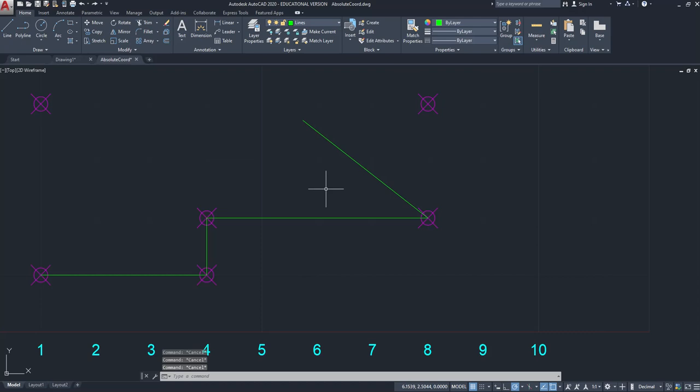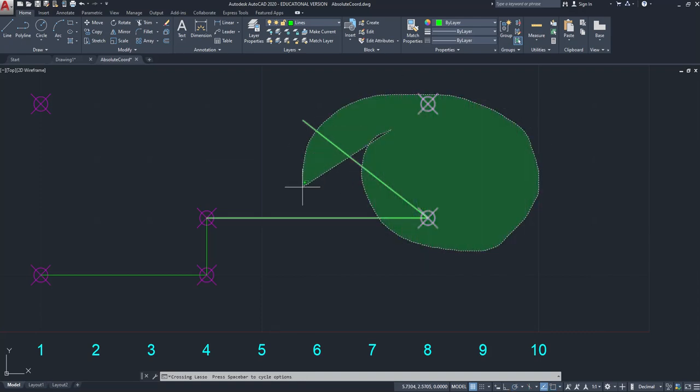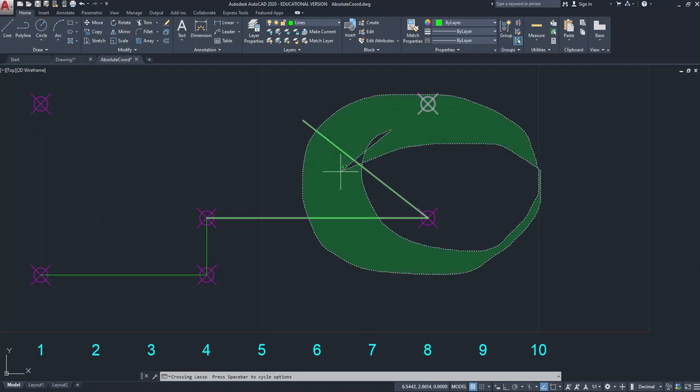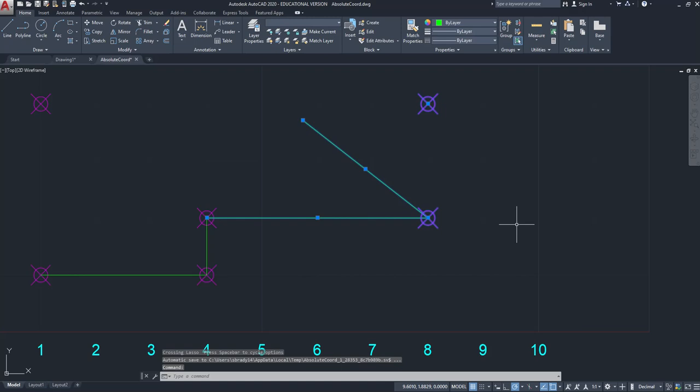There's a couple of other selection methods in AutoCAD you need to know about. We have the lasso, which I don't really like, but I'll show you. And then we have selection windows, and they function a little bit differently. If you click in space, meaning the black area here, and I click and hold my mouse button down and move, you guys have probably already done this. This is the lasso. I am not a fan of the lasso. The lasso is somewhat new. It's very wild.